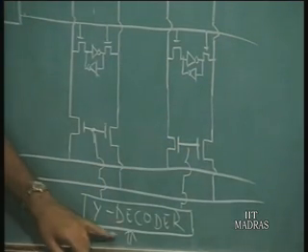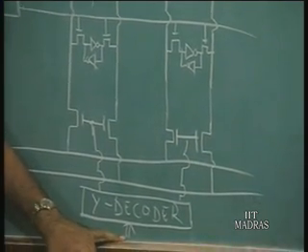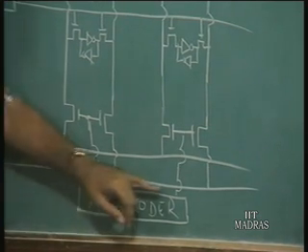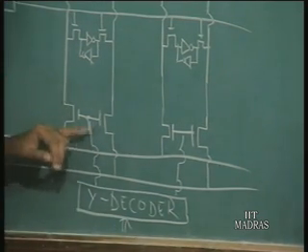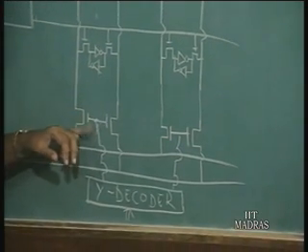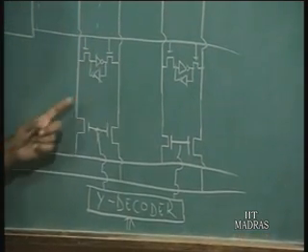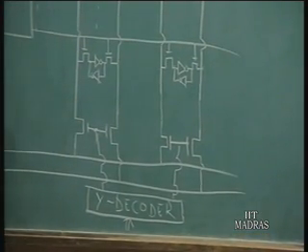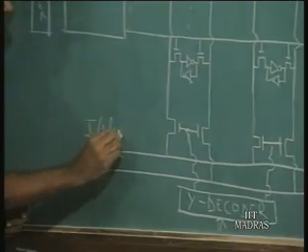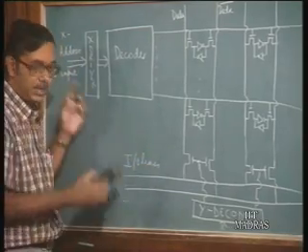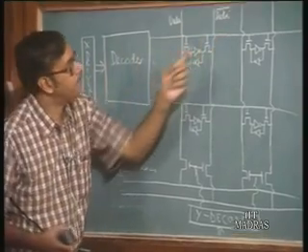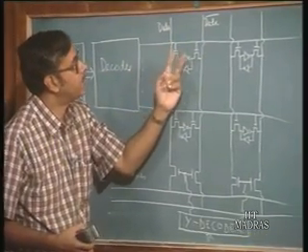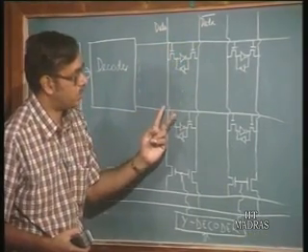So again, depending on the combination at the input here, only one output of the Y decoder is going to be high. So it basically selects one particular column. So only the output of one particular column is connected to the I/O lines. So depending on the input address, one row will be selected, which means that one particular cell in each column is going to be selected.